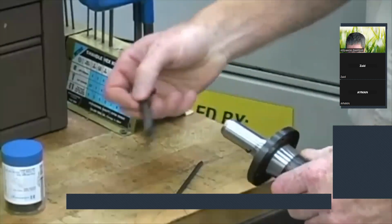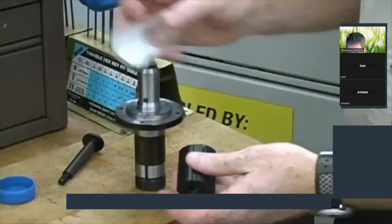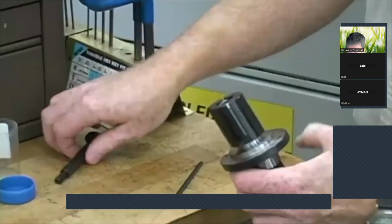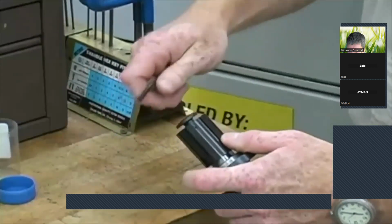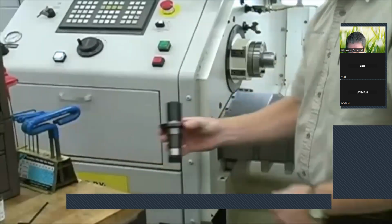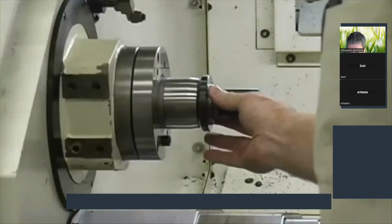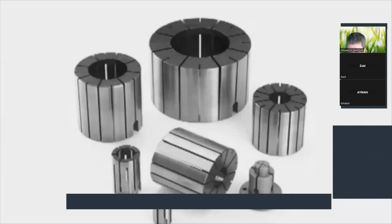Unscrew the draw plug from the end of the arbor and slide the collet over the arbor, aligning the collet keyway to the key on the arbor. Screw in the draw plug to secure the collet in place. Align the collet keyway to the spindle key and slide the assembly into the spindle. Return to the drawbar access door and turn in and tighten the locking bolts.